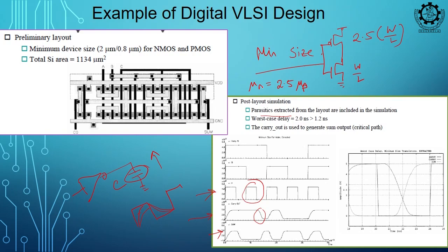So, the NMOS is doing which portion? NMOS is pulling the output to the 0. So, if you make it W by L, PMOS also W by L, you will be seeing that it is going to 0 sharply, but it is taking time to go to 1. Why?